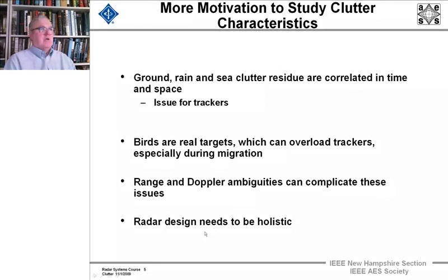clutter. You're going to try to get rid of this clutter with Doppler processing, and we're going to spend a considerable amount of time, many lectures, looking at how to suppress the clutter. Now, if we don't suppress it below the noise, there's some residue of the clutter backscatter that's above the noise levels in your receiver. If you don't have enough dynamic range, you don't have enough bits in your A to D converter, that sort of thing.